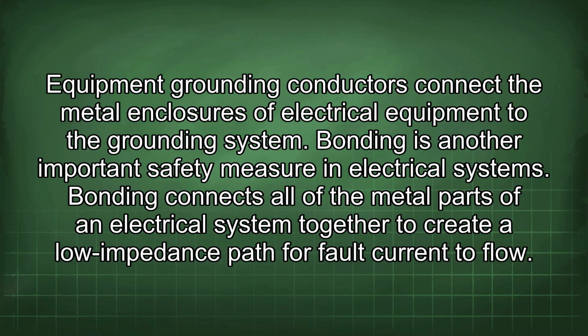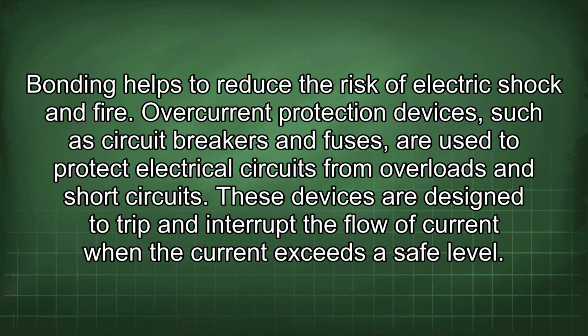Bonding is another important safety measure in electrical systems. Bonding connects all of the metal parts of an electrical system together to create a low impedance path for fault current to flow. Bonding helps to reduce the risk of electric shock and fire.